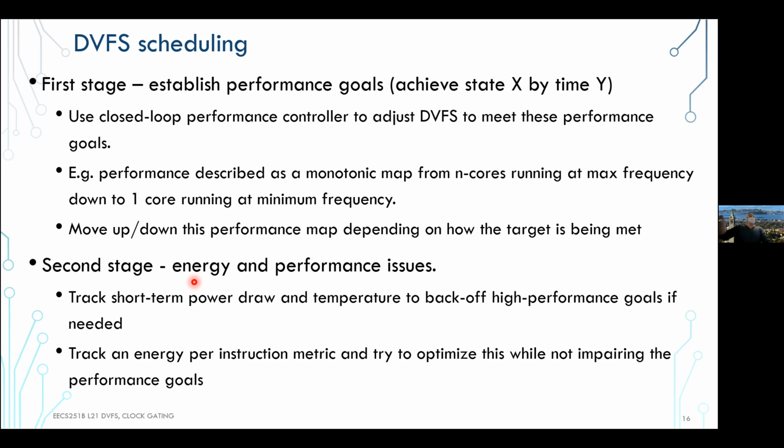I'm not operating at max voltage at this point, but it just happened to be a long enough window that my whole package heated up. And now temperature is a third variable that we didn't talk about. Every voltage frequency curve is parameterized by temperature, right? So that one optimal line that I have actually becomes a family of lines that's temperature dependent.